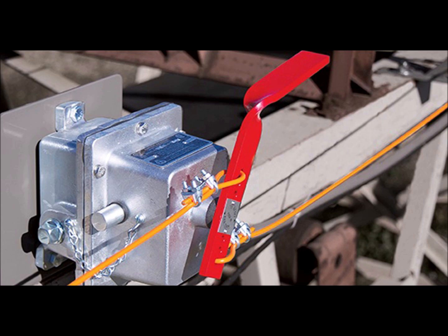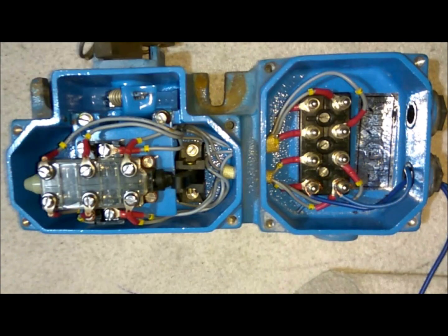The silver part is the PCS, pull cord switch, and the ropes are connected. So whenever we need to stop the conveyor, we will pull the rope, and the ropes are connecting one PCS to another. The internal part, or internal connection, of the PCS will look like this, and this is the same for the BSS, that is belt switch, which we will see ahead.